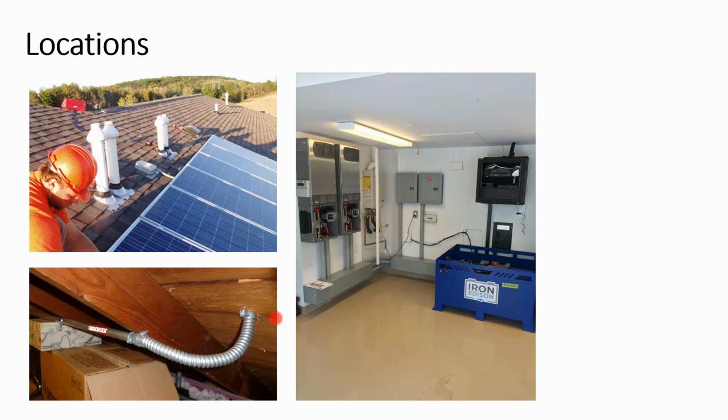Well, this is actually why there's a requirement in code that says you have to seal the inside of your conduit whenever it crosses any temperature differential, actually. So not just between the roof and the attic, but if you're going from an unheated space or an unconditioned space to a conditioned space, just having a temperature differential can cause condensation to accumulate inside the conduit. And so thus just the humidity in your air can cause it to rain inside your conduit.